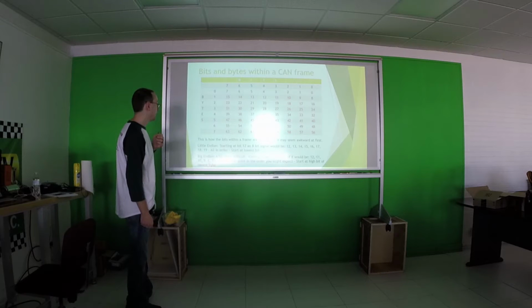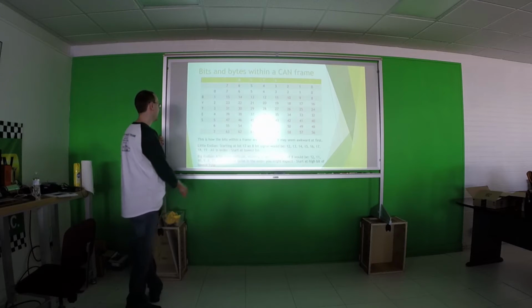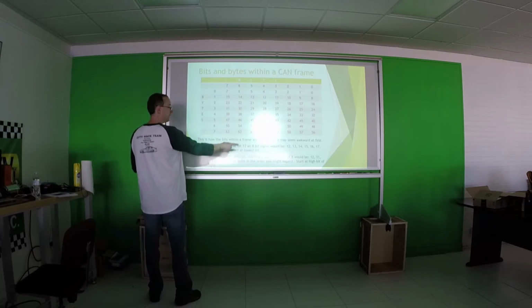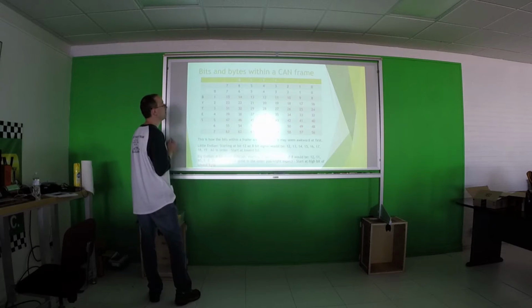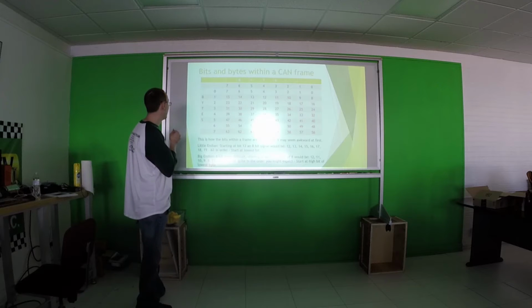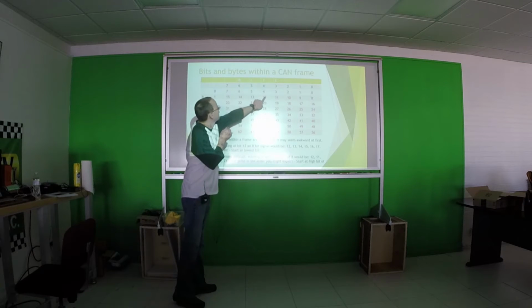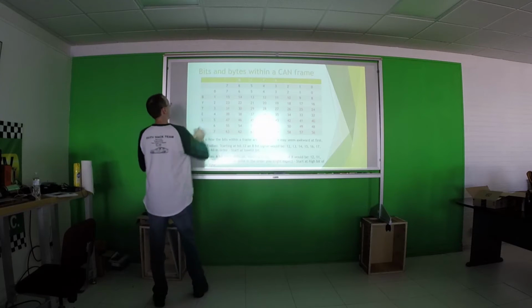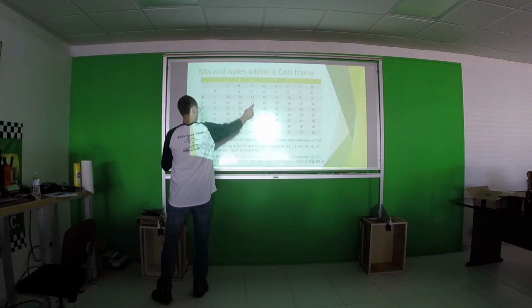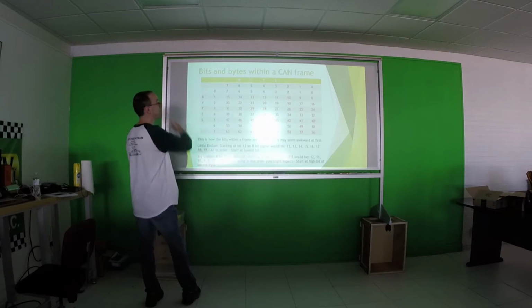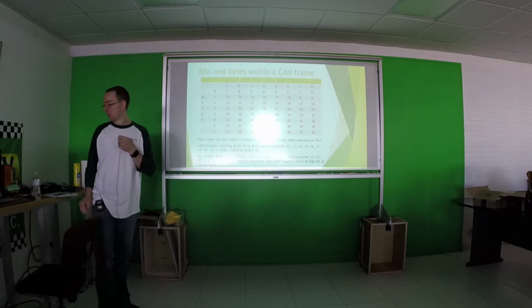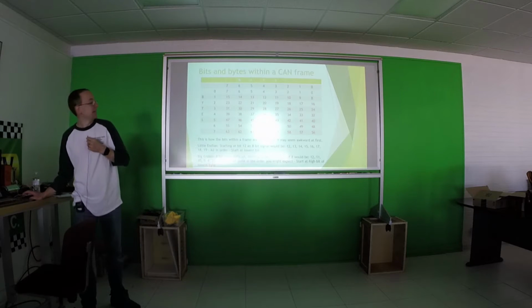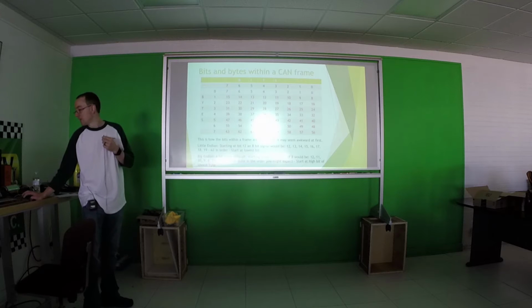The weird one, and unfortunately Tesla does do it, storing in big endian, you will sometimes get, you can see here I showed, if you started an 8-bit value on 12 in big endian, it would literally go 12, 13, 14, 15, and then start over 23, 22, 21. You know, it goes from the opposite direction. Believe me, it's confusing. But that's kind of necessary to understand DBC files.